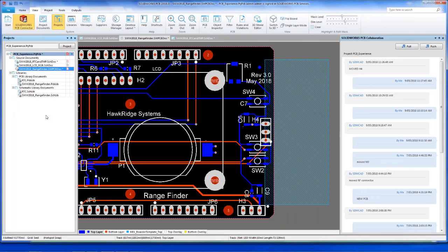Can you export a similar model from Altium? I rarely want that much info in my SOLIDWORKS file as it gets super slow. Can I export a dumb solid from SOLIDWORKS PCB or export a light assembly? The way to do that, you can actually create a variant in Altium and basically unstuff those models that you don't want to see.